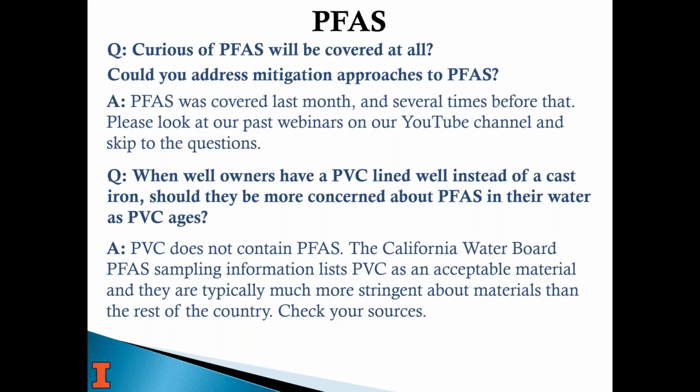They're folks you can count on for new technologies, whether they're good or not. They're well in the game, and they're professional. On their website, there was information on how to sample for PFAS, what kind of vessels to use, what kind of fittings you shouldn't use, all that stuff. And they listed a bunch of PVC-like compounds that can be made into fittings or pipes, but not PVC itself. And it actually says PVC is an acceptable material. So my advice, if you found something on the web that said PVC contains PFAS, it does not.